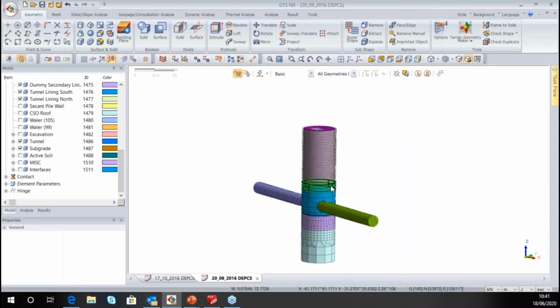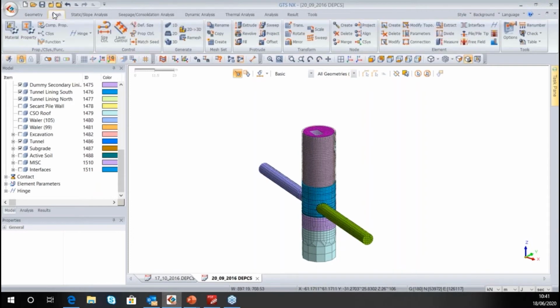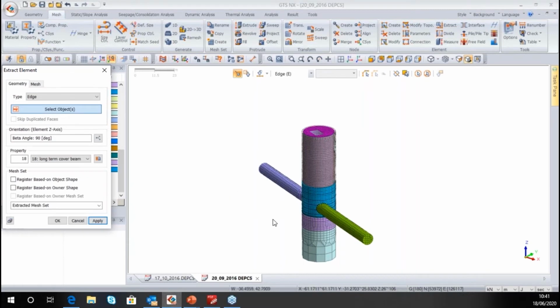And the other thing in terms of generating mesh, so you generated the mesh of all your soil elements. You can generate the mesh for your structural elements by just extracting them from the geometry that was already being created. So the geometry has been used to mesh up the whole continuum. This extract elements function is then useful for just going in to a given geometry element.